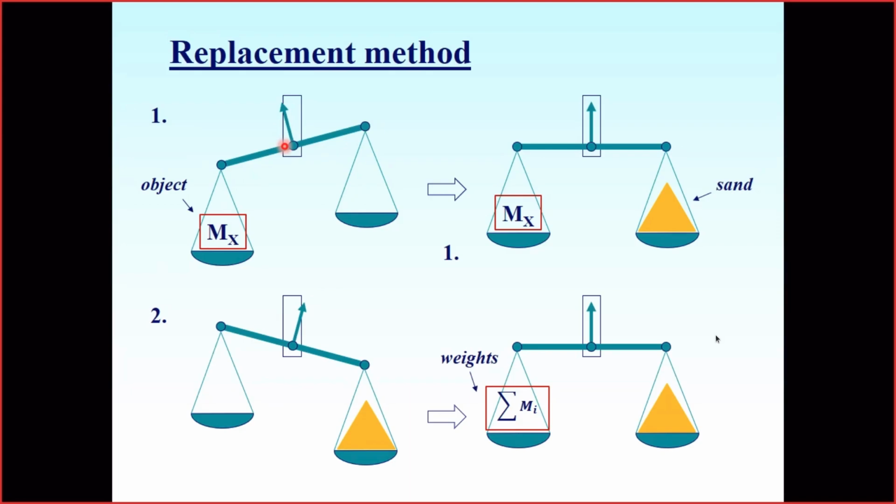But if I have an accurate counterweight, what should I do? I put my object on one side of the scale, and I add some arbitrary thing as a counterweight. I may use, for instance, sand. In real manual measurement, sand is used very often because you may dose your sand very accurately, grain by grain. I put it on the other part of the scale to balance them. Then I remove my measured object and start to add calibrated weights until I get my scale balanced once more.